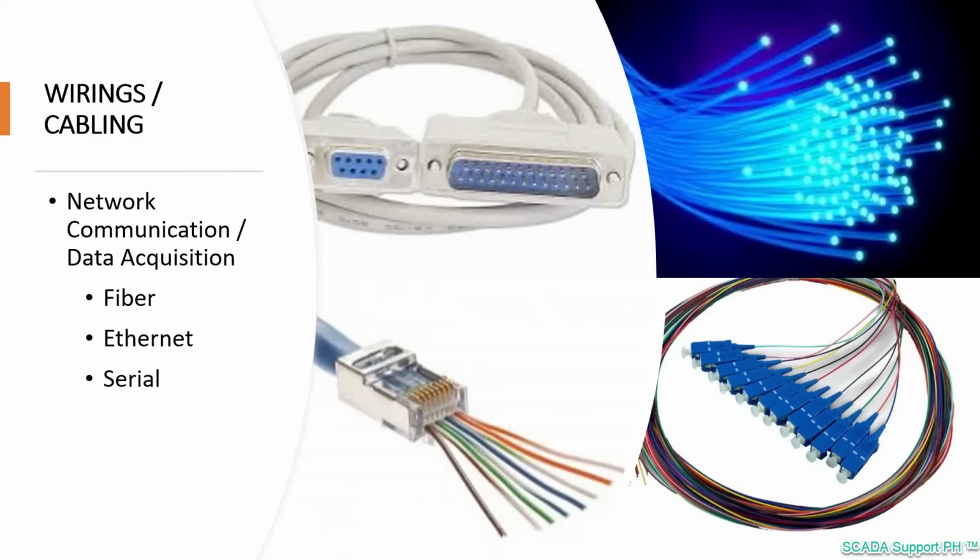These are usually installed between the SCADA Communications Panel on the skid and the substation where your SCADA servers are located, since Ethernet cables are limited to a maximum length of 100 meters or around 230 feet. Revenue grade meters often use Ethernet cables, while inverters are more into serial communications using RS-232 or RS-485.